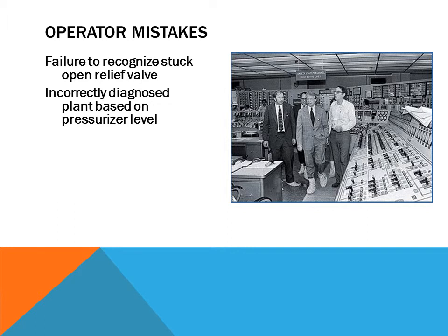So when the casualty first happened, let's step back just a second. When the casualty first happened, the steam generator had water still in there. So the plant scrams and the steam generator is still removing heat. Well, as that's happening, the pressurizer level starts to fall. The operators correctly start pumping in water. However, the water coming in was quicker than the water leaving. So pressurizer level rose and the operators thought things were under control.